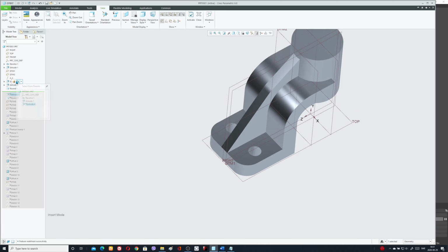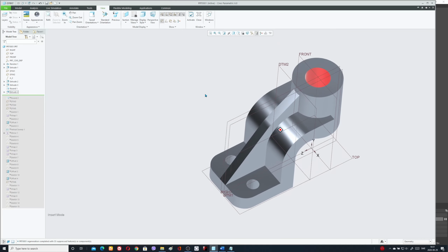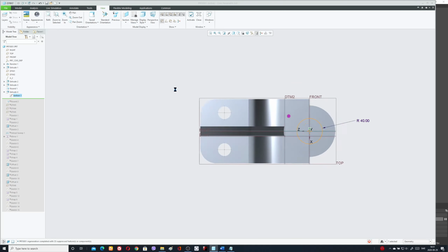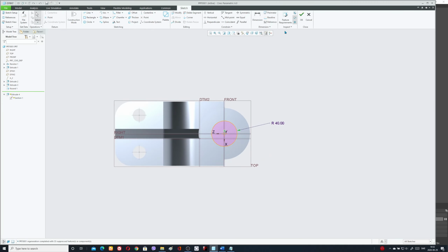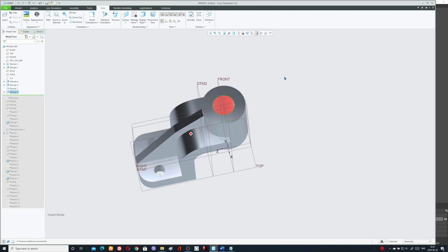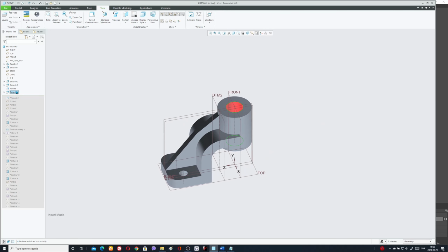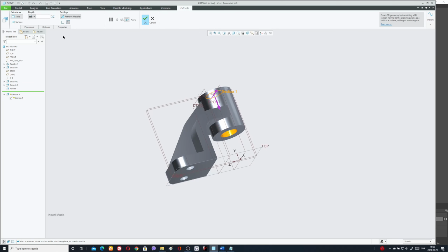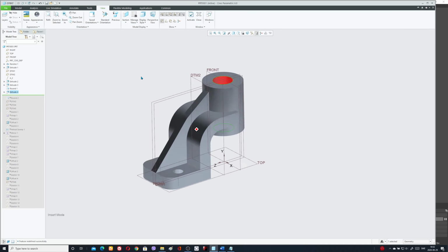And after that, we're taking this hole here. I did that with extrude. And this one here is 40 millimeters. I go out. And the hole is to the next section, with this one here. It's okay.